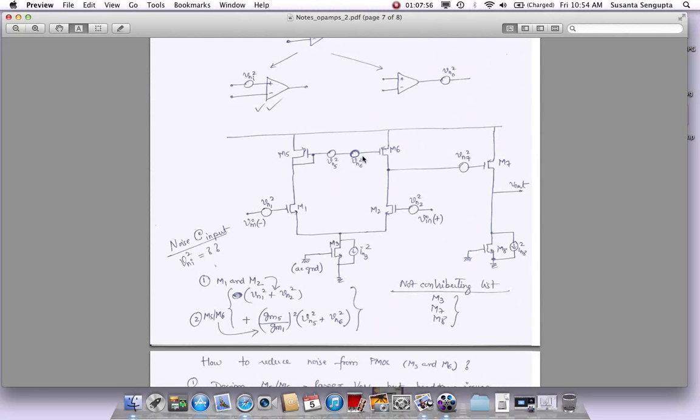As I said, this voltage to current is given by this term here, but I also have it divided by GM1 square, because if you convert this current back to a voltage, you have to divide by the transconductance of the stage, GM1 being equal to GM2. If you work it out, you'll see they both show up equally, whether it's from this guy till here or this guy till here. So the noise of 5 and 6 will show up, but with a ratio.